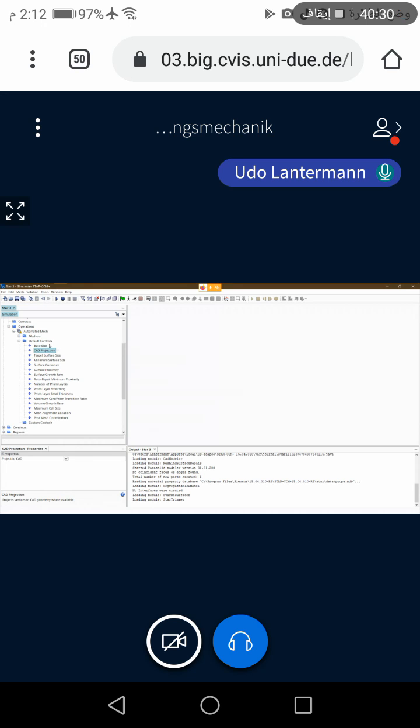Projection is used by default, so it's fine. Target surface size, that's the size of the surface cells, and that means the target size, which is chosen on average. So this is 100% of our base size. That's fine. We use this value.